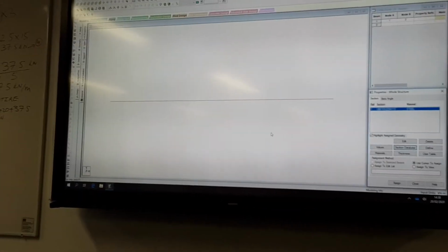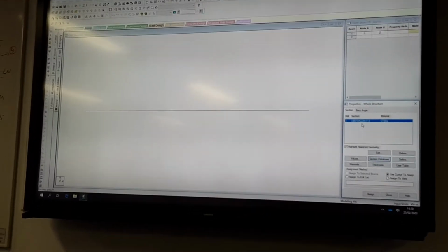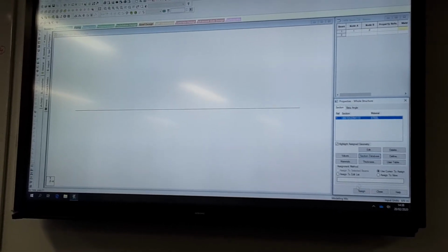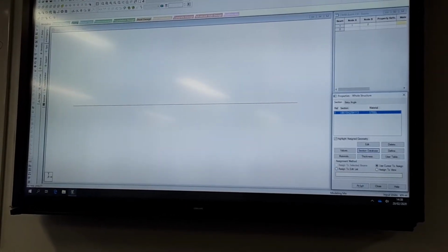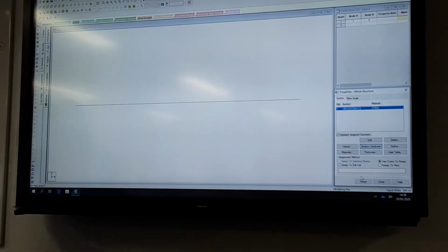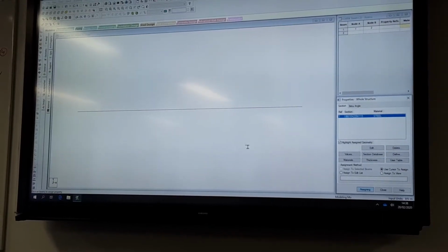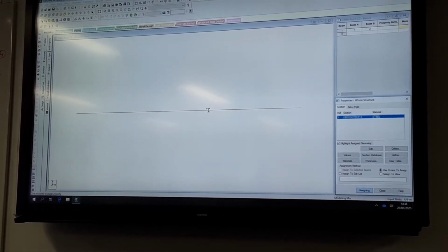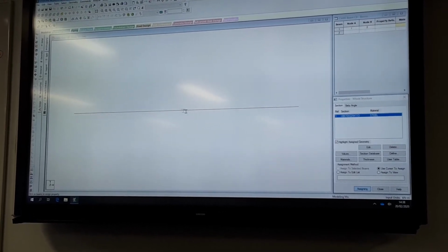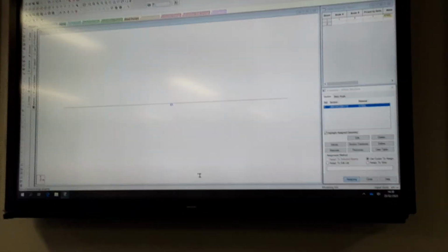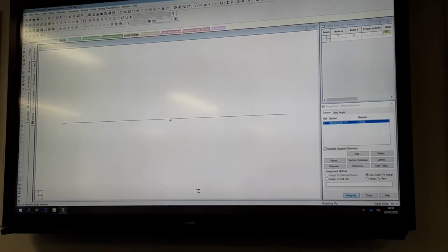You can assign any section that you want. Now the section is defined, and now you have to assign that section. So click on this assign button over here. Okay, if you can see the assign button at this point, click on assign, and then it says assigning, and you can see that this icon appears. Now click on the member itself. If you click on the member, then it should actually assign. Yes, fortunately, finally it's been assigned.